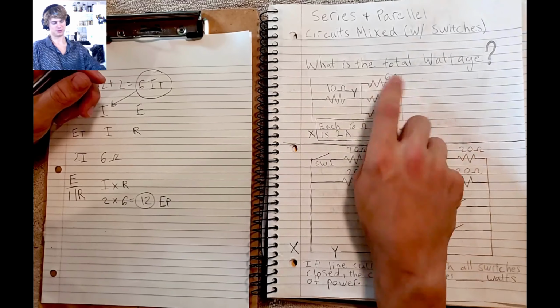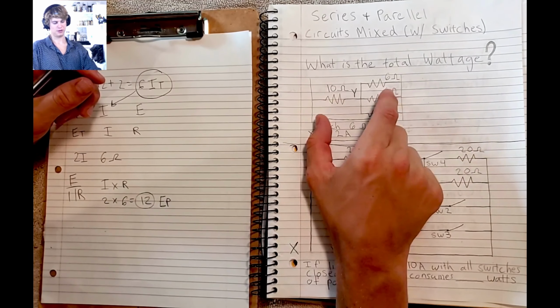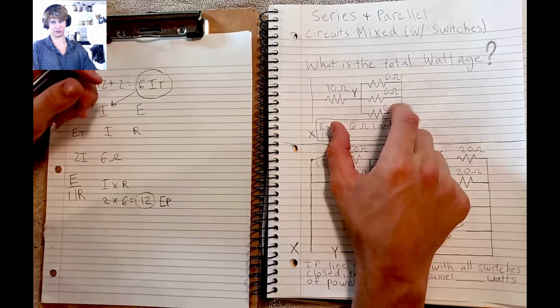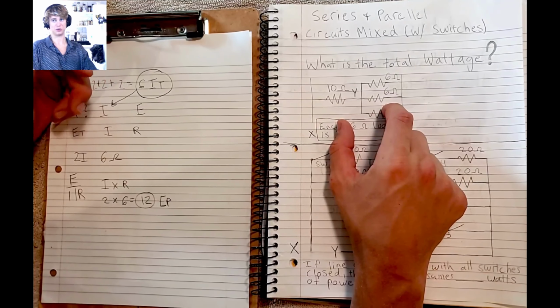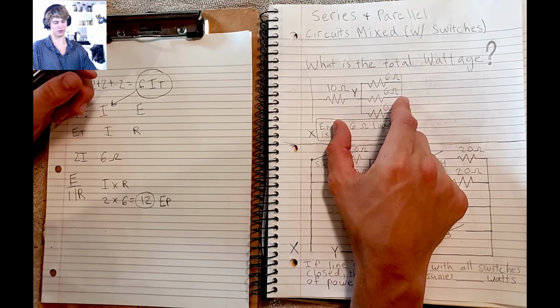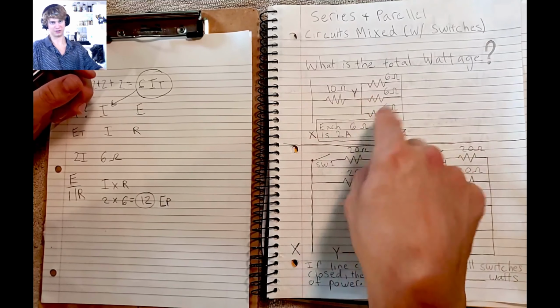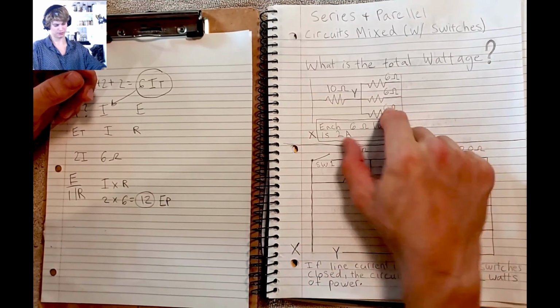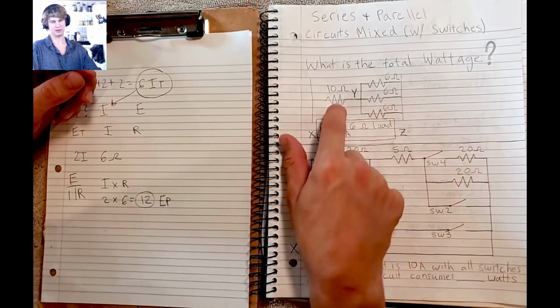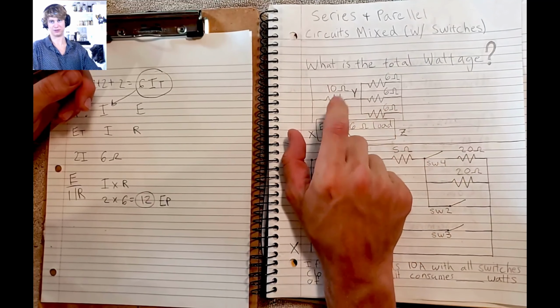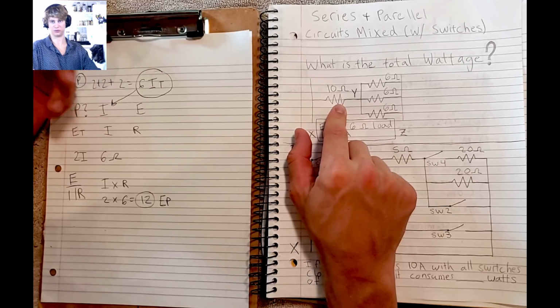And since these are all the same voltage, if we add the voltage that we figured out for our parallel section, which is all the same, which again, the total voltage for a parallel circuit would be the same as each one. So we know that this total section of this parallel circuit is going to have those 12 volts. If we add that to this section of the series circuit, if we math out these volts, then we're going to have our total voltage.